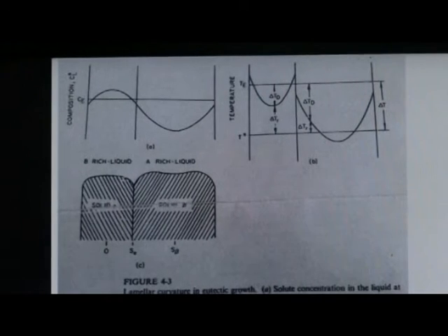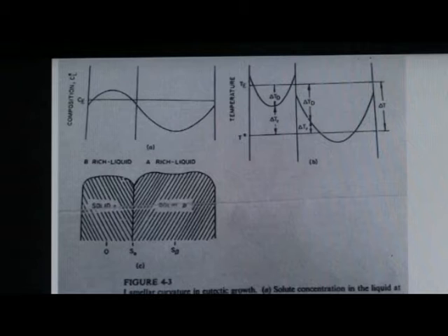In this figure, we see that the actual interface temperature T* must be essentially constant in non-facet eutectics. This is because the curved surfaces of the lamellae in these eutectics usually deviate from a plane by less than a few microns. Hence, even if a temperature gradient exists in the growth direction, the variation in temperature from the leading to the lagging part of the lamellae is negligible. The interface is maintained isothermal at T* by the lamellae adjusting their radius of curvature locally.